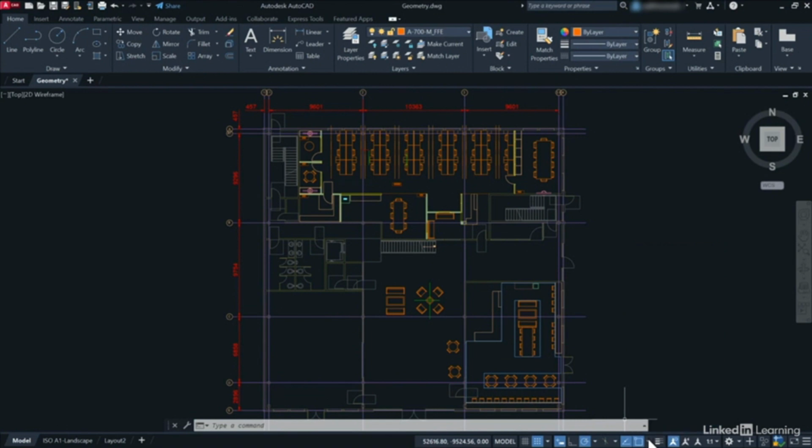That will close that menu. Then make sure that Object Snaps is on. It should be blue, not grey like that, so blue. And also Object Snap Tracking should be on, so that should also be blue like that. You also want to make sure over here that your polar tracking is on as well. That should be blue, and if you click on the flyout arrow there, just make sure that's set to 45 degrees for the moment, like so.